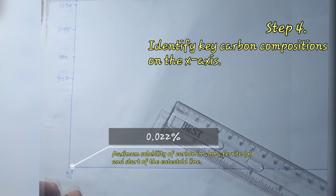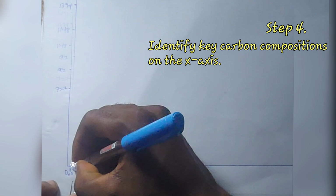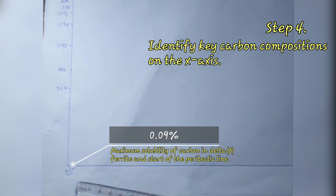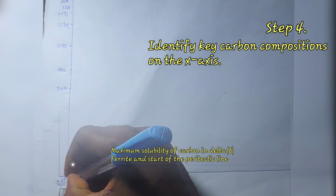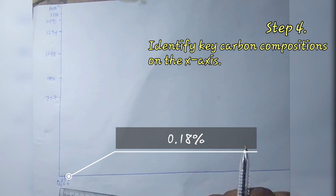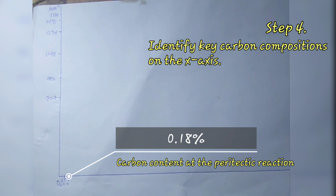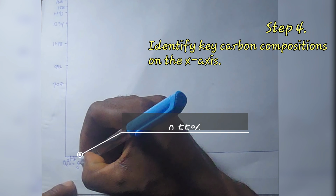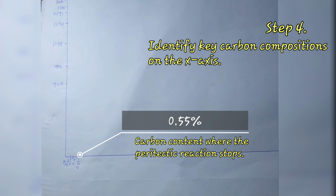0.022%. Maximum solubility of carbon in alpha ferrite and start of the eutectoid line. 0.09%. Maximum solubility of carbon in delta ferrite and start of the peritectic line. 0.18%. Carbon content at the peritectic reaction. 0.55%. Carbon content where the peritectic reaction stops.